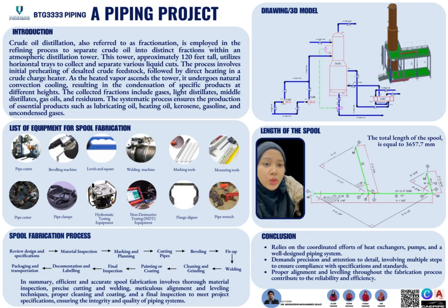So I will continue with the calculation of the length of the spool, including the gasket, flange, fitting, and the root gap for bevel butt welding. The tables that I refer to are the dimensions of class 300 flange and the butt welding pipe fitting dimensions, standard ANSI B16.9.